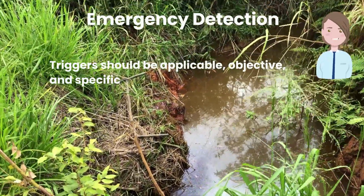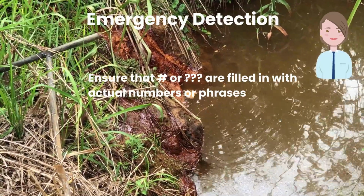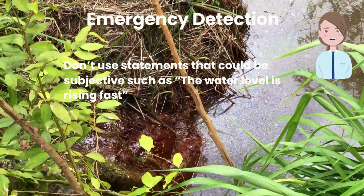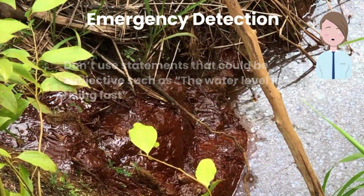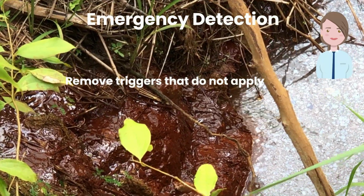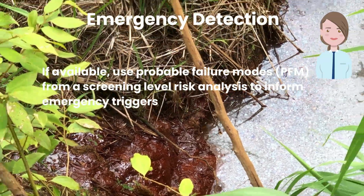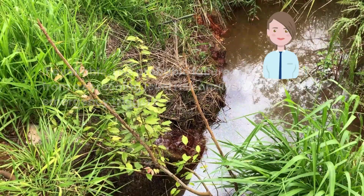Triggers should be applicable, objective, and specific. Ensure that hash or question marks are filled in with actual numbers or phrases. Don't use statements that could be subjective, such as, "The water level is rising fast." Remove triggers that do not apply. If available, use probable failure modes, PFM, from a screening level risk analysis to inform emergency triggers.